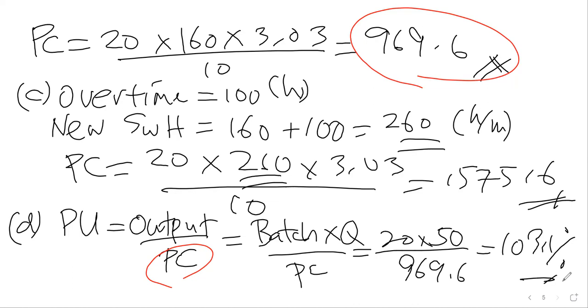So you know already how to calculate the MLT, how to calculate the RP, rate of production, based on TP, time production, and from there you also know how to calculate the plant capacity and plant utilization. So I think we cover all the manufacturing and costing.